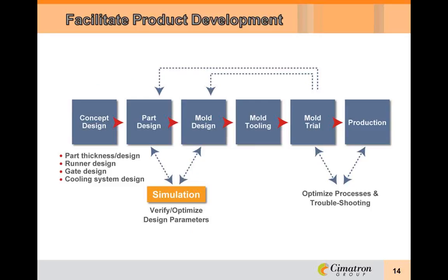With the CAE approach, a process simulation is launched before the prototype mold is ever constructed. In other words, prototyping is done on the computer. In the design phase, a part designer evaluates the influence of material selection and processing on the various part specifications. The analysis is based on physics principles and actual conditions, rather than a rough estimate from handbooks. Part wall thickness can be optimized to facilitate its processing feasibility and product performance. Part design is very flexible since the real mold has not been built yet.